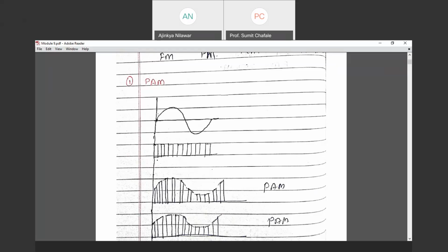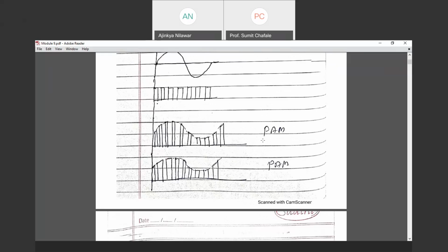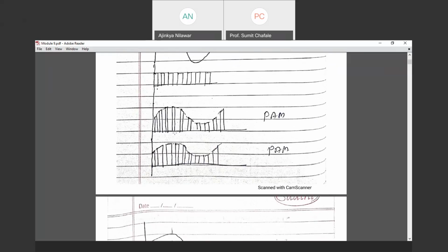This signal starts with the sine, hence the amplitude A multiplied by sine omega into t. What is T here? This is the time period, T is equal to 1 by f. So the mathematical representation says this is the signal of amplitude A, and since it is starting from 0, it is sine omega t. Then these are some pulses. That means this is the carrier which will carry information. If the pulse modulation is in analog form, the PAM looks like this.